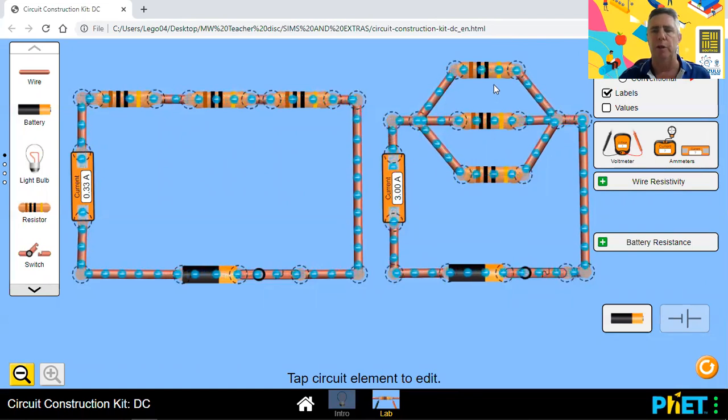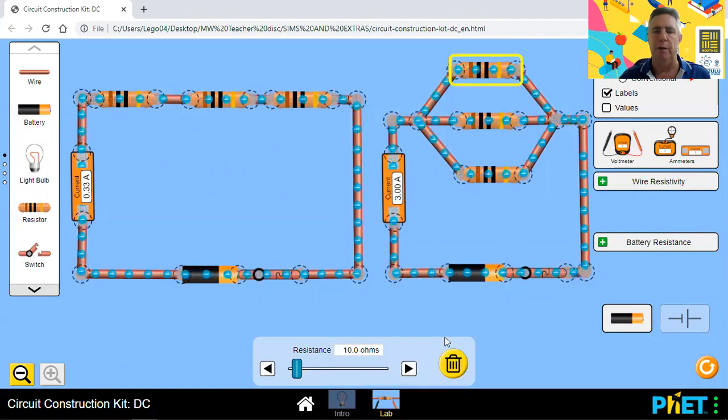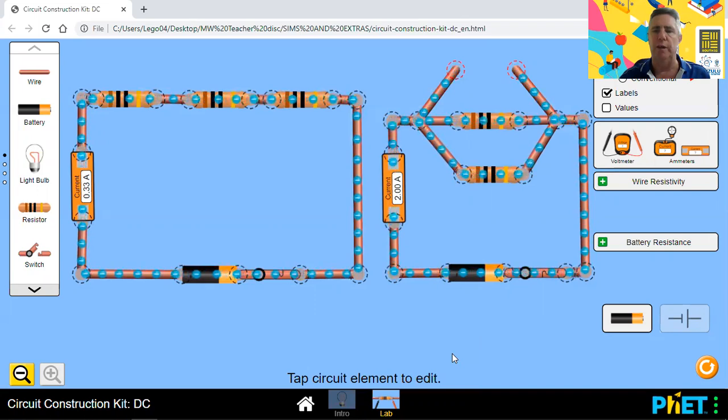Let's look at the parallel circuit. If I take that resistor and I remove it, you can see the current continues to flow. Obviously, there's no current in the top branch now, but it has two other options. And that's why the current doesn't stop flowing. This is why this is much better for something like household lighting. Otherwise, if one bulb goes out, all of them go out.